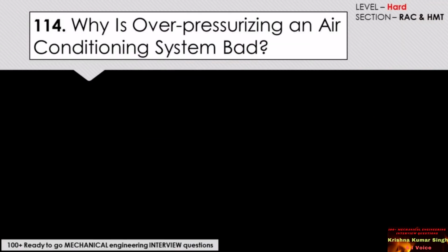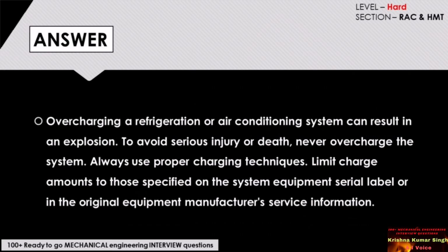Why is overpressurizing an air conditioning system considered bad? Overcharging a refrigeration or air conditioning system can result in an explosion. To avoid serious injury or death, never ever overcharge the system. Always use proper charging techniques. Limit charge amounts to those specified on the system equipment or by the manufacturer's service information.